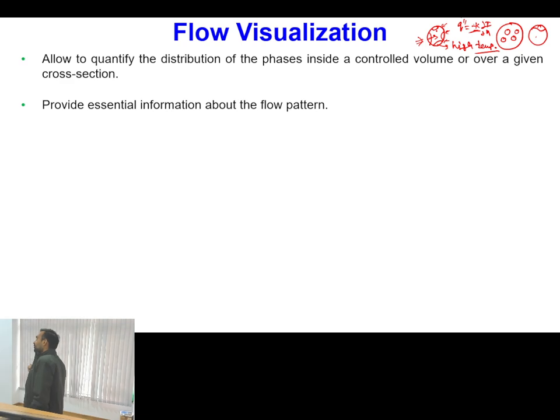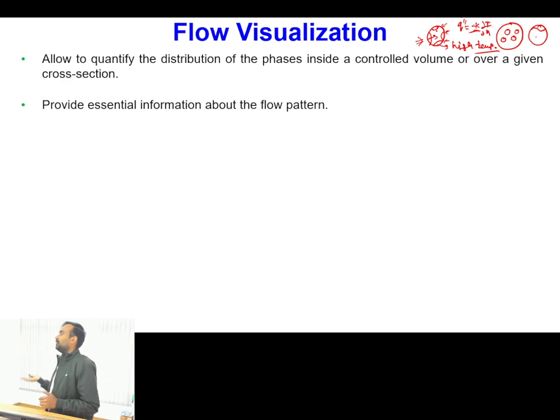So if the inside fluid is taking heat flux at a lesser rate, then the overall surface temperature of the pipe will be increasing, because additional heat is being stored in the pipe surface. Okay, and if you have liquid contact, then because of the high thermal conductivity, the heat transfer rate will be fast, and if it matches well with the heat flux supplied, then the temperature will stay at a constant value. Or if the heat transfer rate is faster in the liquid than the supplied, then even the temperature can go down.